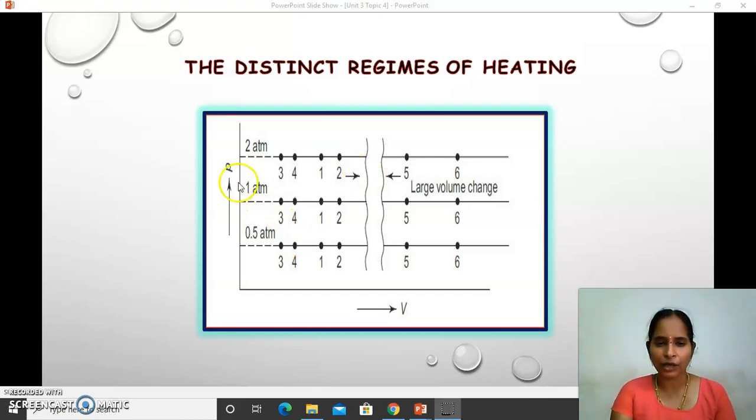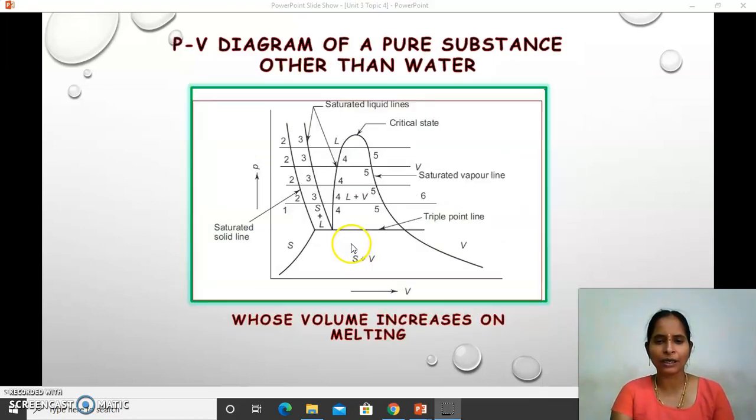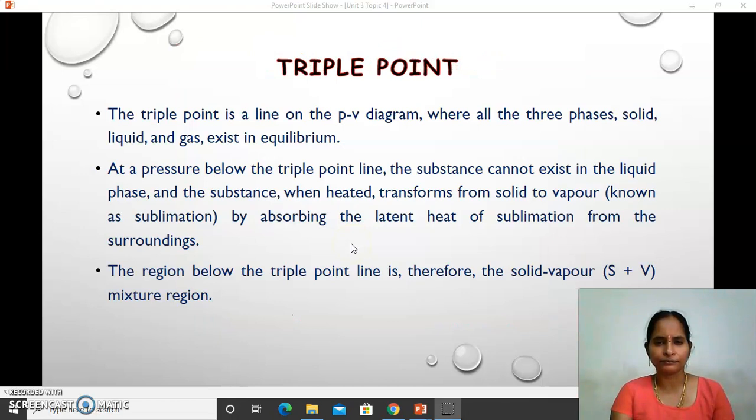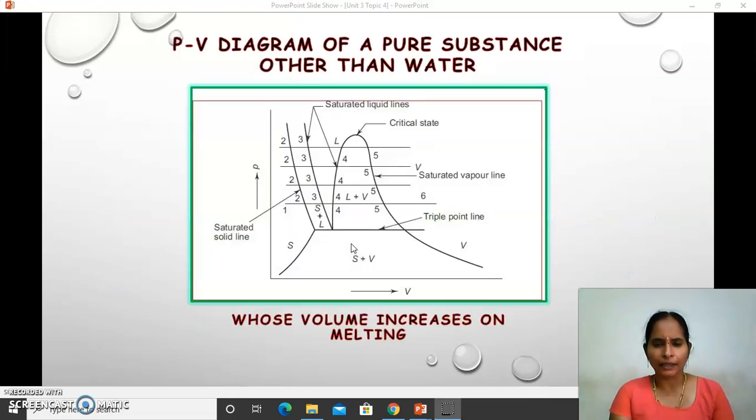Okay, so when you conduct the experiments at higher pressure, the duration of the phase change would be reduced, and the properties would also change. Okay, so here you have to learn that a very important thing is saturation temperature, saturation pressure, and how the process takes place, especially for steam.